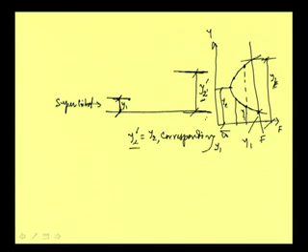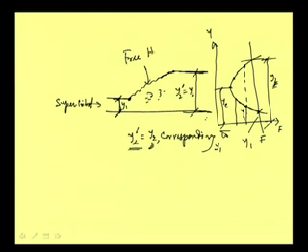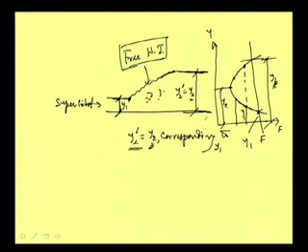Now, if the tailwater depth y2 dash is equal to the sequent depth y2, then the flow will jump from y1 to its corresponding sequent depth like this, and in this part we get a lot of turbulence. This sort of jump we name a free hydraulic jump. We are not forcing the hydraulic jump to occur in a particular place. We are not doing anything. Our tailwater depth is just equal to the required sequent depth for this initial depth, and that is why the jump occurs freely, and we call this jump a free jump.